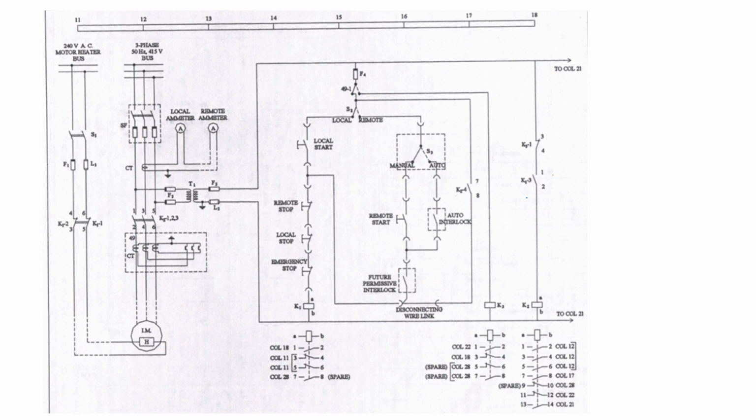So, as mentioned earlier, the motor can only start if permissive signals or interlock mechanisms are provided. When in automatic mode, the motor will start automatically if the permissive and interlock permits are available. In case the motor becomes overloaded, the overload relay will detect it, which is number 49, we already talked about this, this is a thermal overload relay. So the 49-1 relay contact in column 11 will change its status.